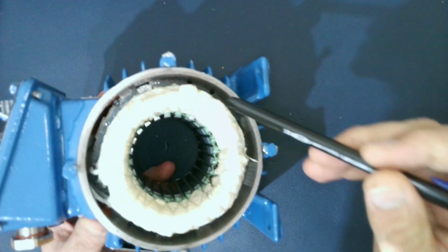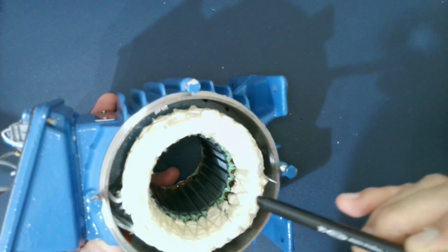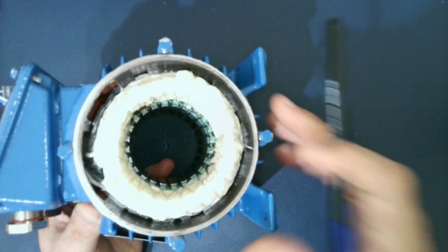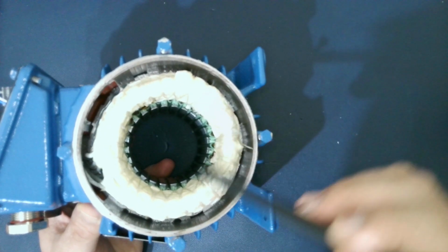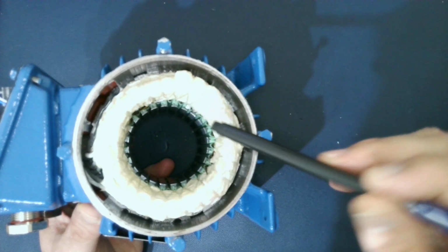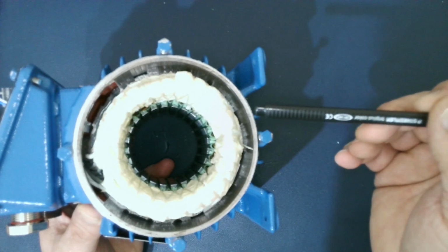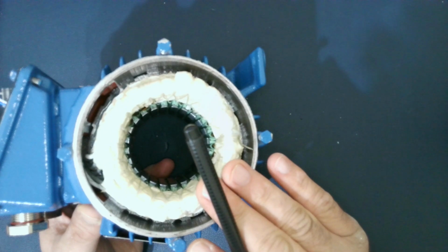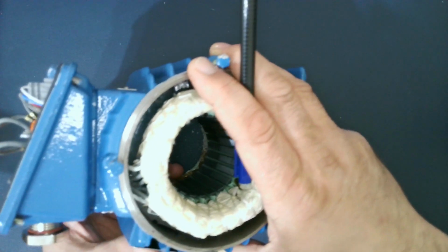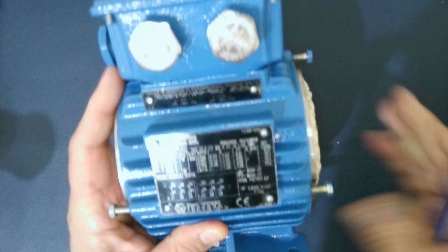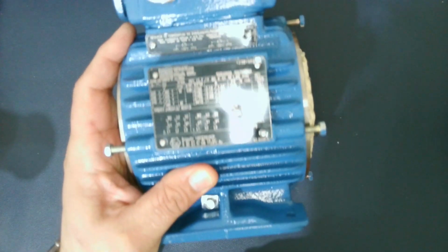But now we look here, we have a North Pole and South Pole. So this machine is a 2-pole machine. So what would be the case if I didn't know from the winding arrangement that that one is a 2-pole machine? And usually you cannot open the machines all the time to look at the winding from inside. So you need another method or alternative method to know the number of poles. So I'm going to look for the nameplate here.